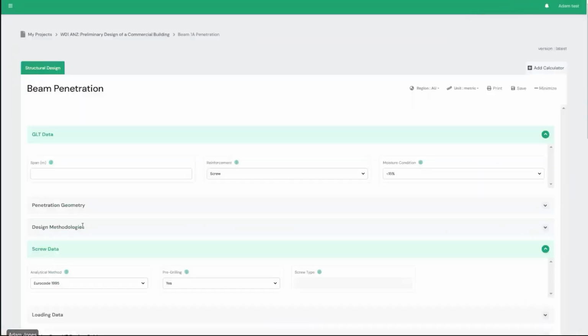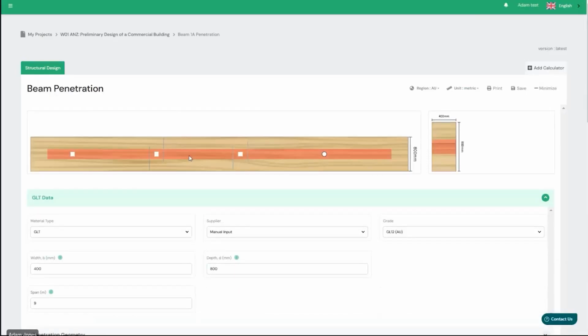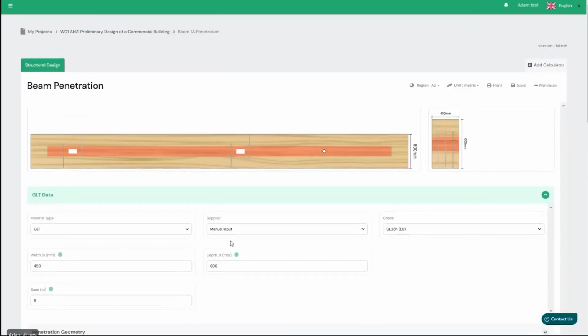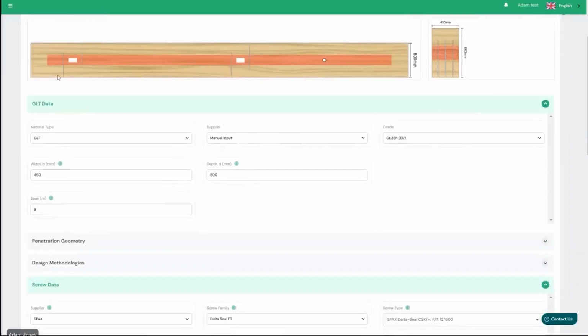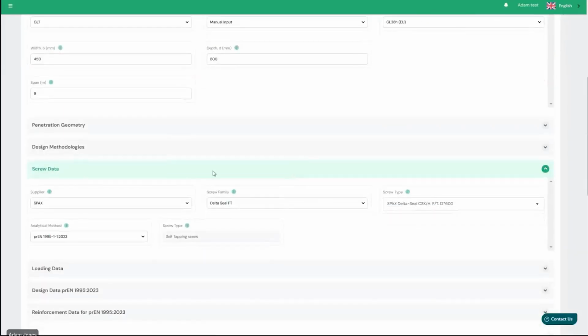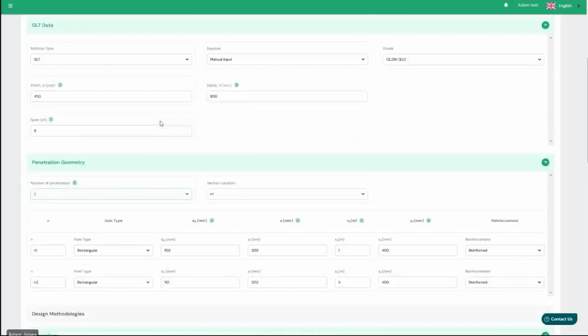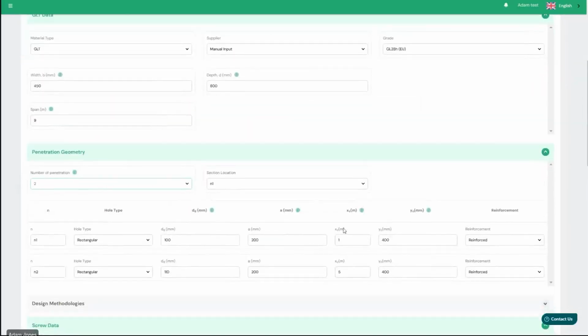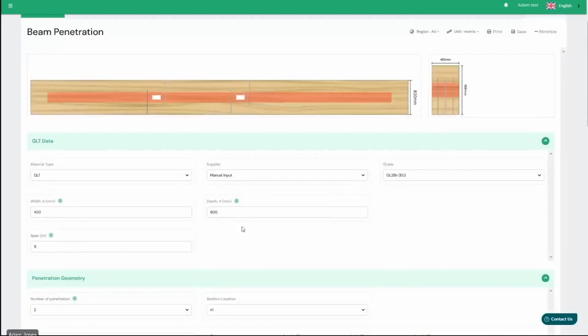And we can load it up. You could obviously create the calculators from the front view as well. So for the penetration, well, this is quite similar to the one I created. I actually saved this exact calculator earlier, preparing for this, but you can see the penetrations. You've got a number of penetrations. So as you go through, you can change the number from 3 to 2 to 5 and so forth. And it's quite easy to work with your mechanical services provider for the project to actually negotiate with them about how to deal with your penos.